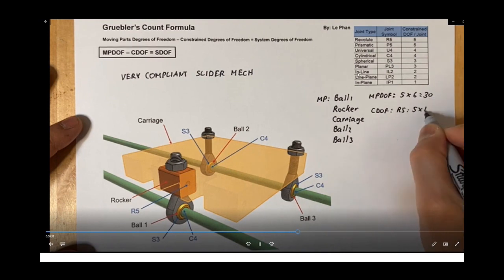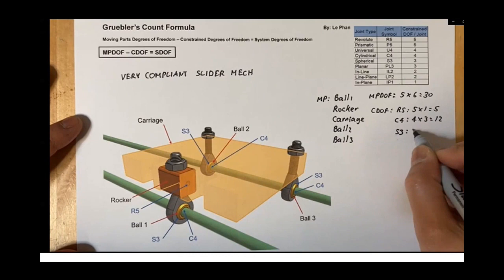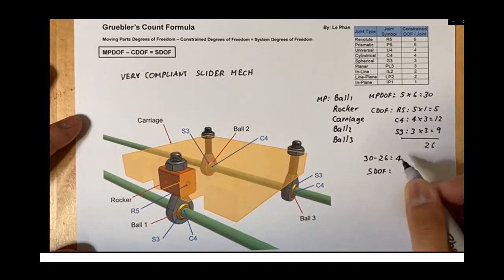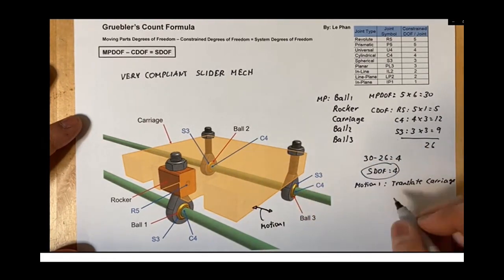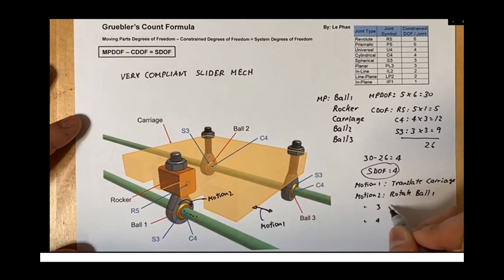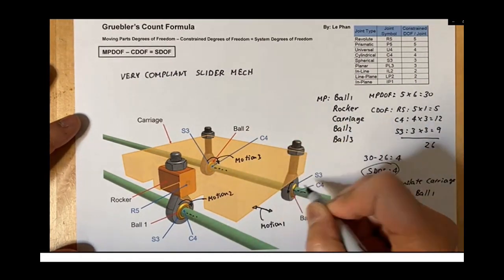I used to design slide tables just like this, and you're exactly right. They would get into a bind, so the technician, we'd have to put enough tolerance in the bolt pattern to make sure everything was parallel and tested. Right. And they were asking like thousandths, within distance of one another and parallelism and everything. And after a while, when things bend and wear, it's going to get out of place too.